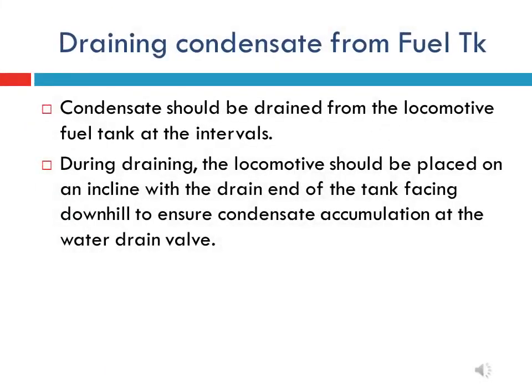For better performance of the fuel oil system and for better health of the engine, we have to drain the condensate water from the fuel tank at regular intervals.